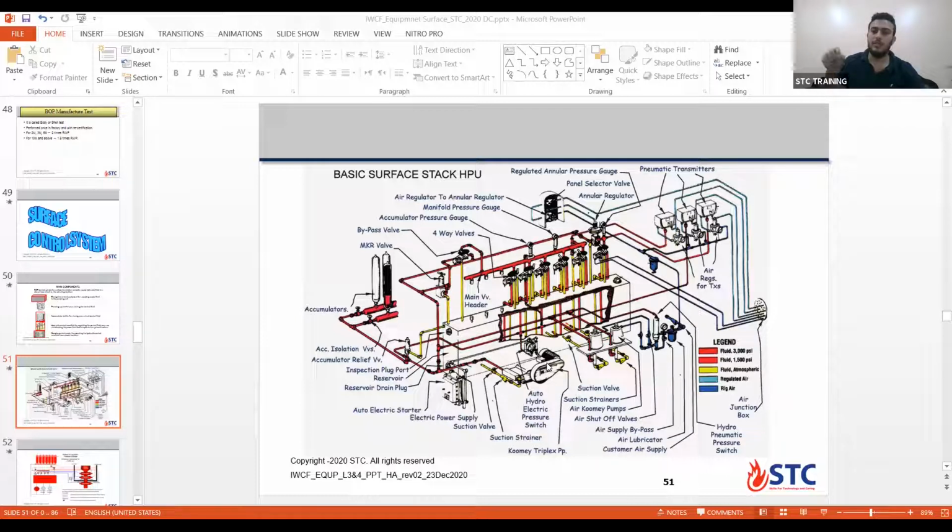Once the pressure in the bottles, or in the accumulator system, drops to 90% of its value, so if it reaches 2,700, the electric pump starts to charge pressure again. For the air pump, it is 5% below that. If the pressure reduces to the limit of 85%, about 2,550 psi, it is time for the air pump to start pumping again to pressurize the fluid into the accumulator bottles.